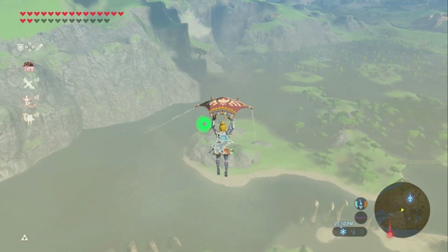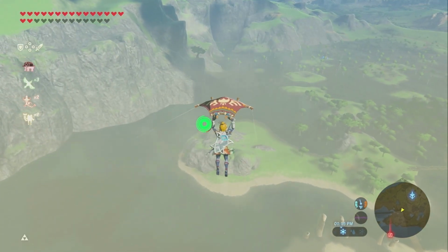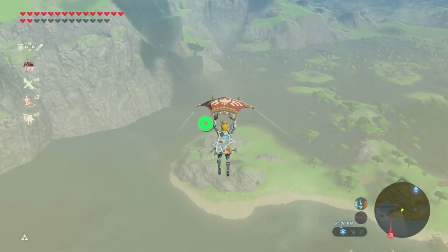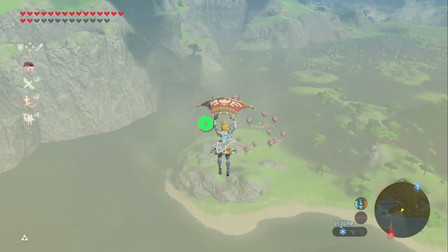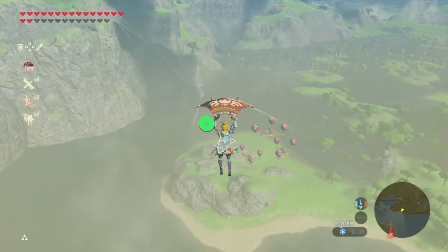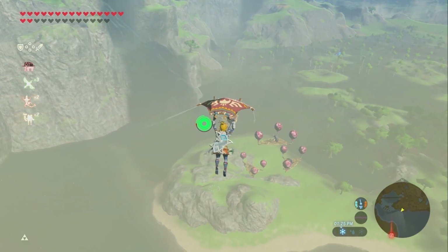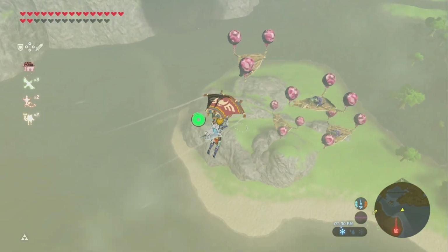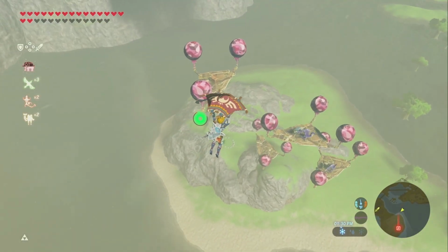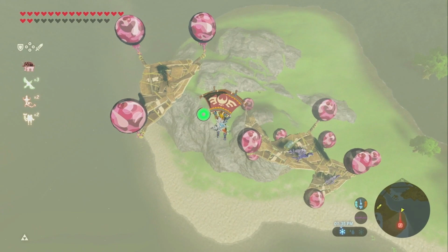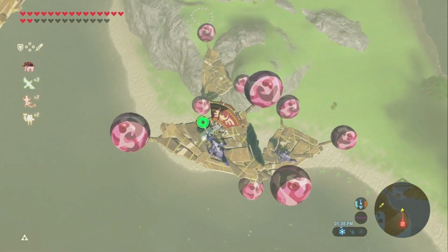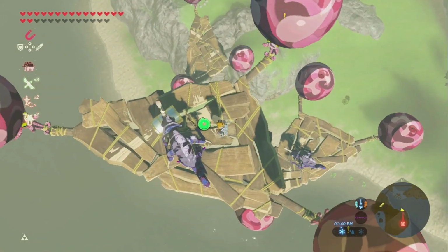12. Improper material used for discharge tube. The material should be rated for water distribution or a listed and approved manufactured blow-off tube. What a weird way to phrase a sentence. 13. The TPR valve or discharge pipe will not drain by gravity. 14. The discharge pipe is connected directly to the drainage system.